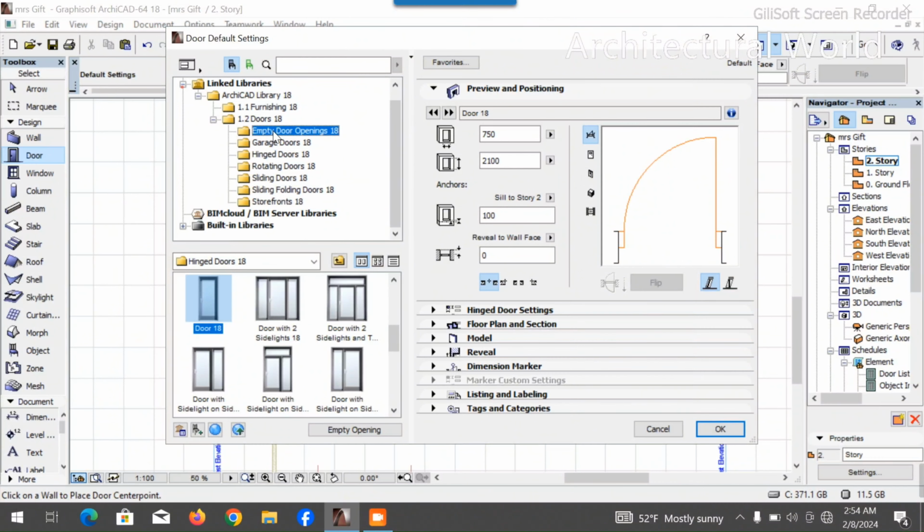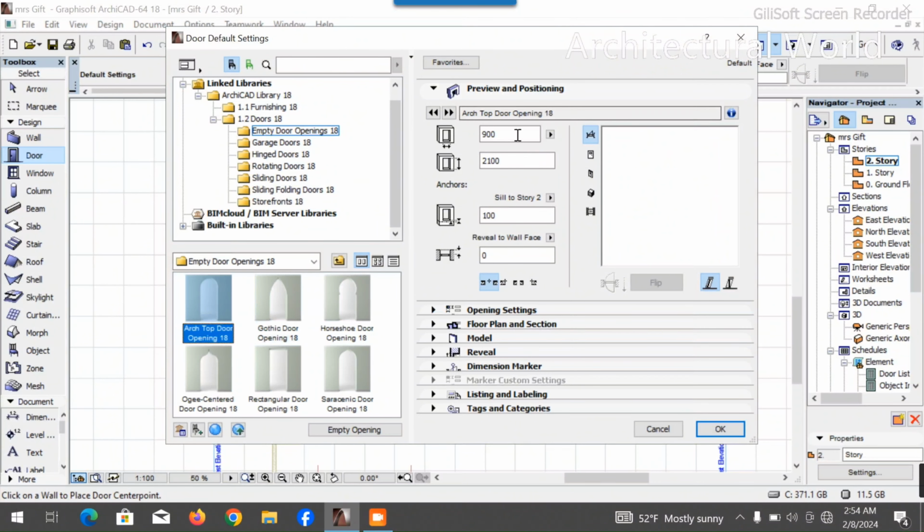Like I said, we'll pick our arc, we'll come to the size, we'll pick 2.650. Now the height, you know, the height of all arc is higher than the main door height. So since the main door is 2.1 meter and they have to be 225 millimeter on top of this, let's assume you should be using 2.4 meter in total.